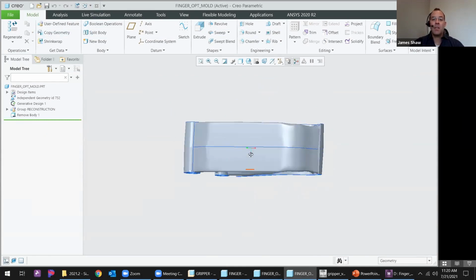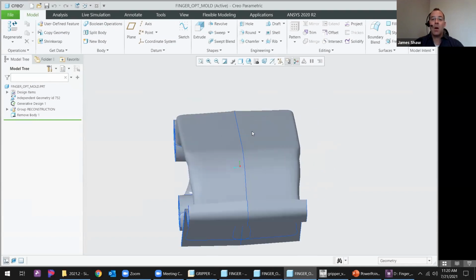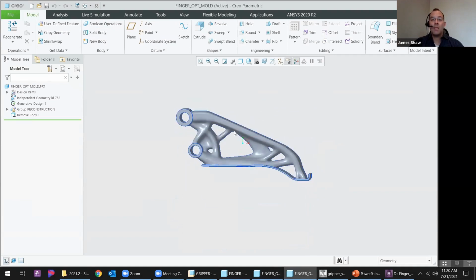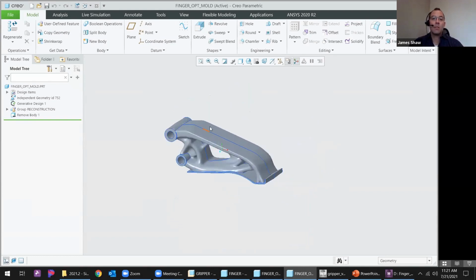In comparison, this is the design for molding. You can see some of the features that we have. You can see our draft angle in there and our symmetry down the middle. We do have that same efficient structure, if you will, but certainly we've got a little bit more mass here. This is going to be a polypropylene, and we've only reduced the mass by 50%. But generally speaking, we have gotten our weight down, which is really, really nice.